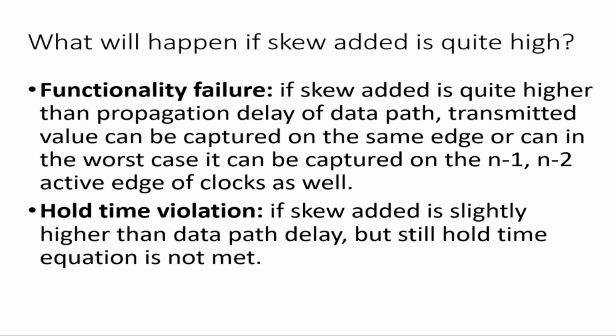And we ensure that the hold time requirement of the second flip-flop is met and data is not received on the same active edge of the clock. Let me repeat again. Hold time violation checks ensure that data is not received by flip-flop 2 on the same active edge of the clock and there is no hold time violation.